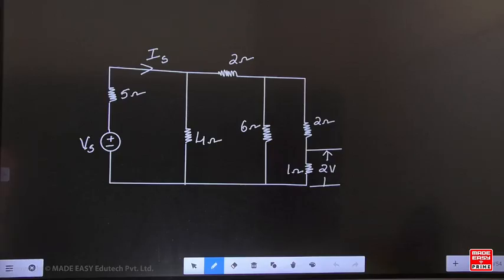Yes, Sachin, your statement is correct. Direction, others already concluded. What is the resistance nature? Absorbing power. Absorbing means current should enter at the positive. In that way, the first two branches are indicated. How did the third branch current come? KCL: incoming current equals outgoing current.